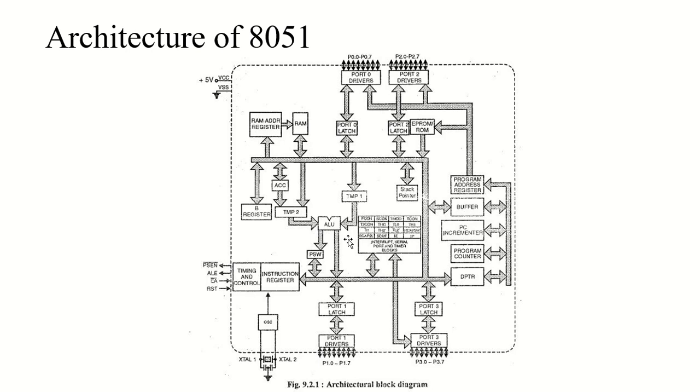Then we have the general purpose area, and as we know, RAM is located in the scratch pad area, and it lies above the bit addressable area that has address from 30H to 7FH, right? So the RAM area can be used as a data RAM, and the memory of this area is byte addressable. So the programmer may declare stack in this area, provided sufficient number of bytes are available.